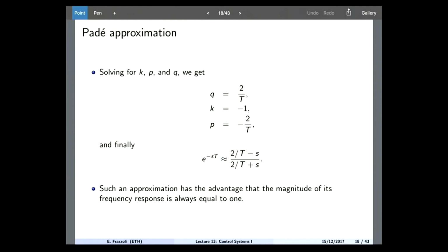If you want to do Bode, write your transfer function in the Bode form. This form is actually neither. If I wanted to do the root locus, I should write this transfer function in such a way that the coefficient in front of the s is always +1. How do I write this in such a way that the coefficient in front of the s is +1?